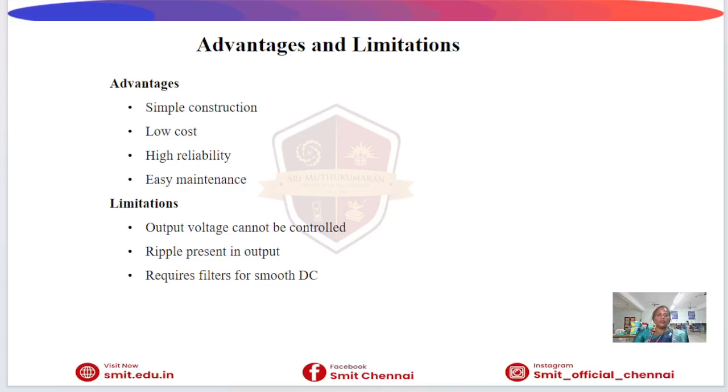However, uncontrolled rectifiers also have certain limitations. The output voltage cannot be adjusted or controlled according to the load requirements. Output contains ripples, which may affect sensitive electronic equipment. Therefore, filters such as capacitors and inductors are often connected to the output to obtain a smoother DC voltage.